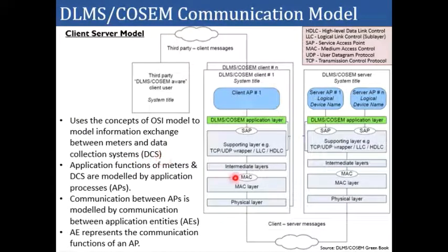Data collection systems are nothing but applications responsible for receiving the data sent by smart meters. Now, application functions of meters and data collection systems are modeled by application processes. So at various ends you will see various application processes, and the communication between application processes is modeled by communication between application entities. Application entities represent the communication functions of an application process.